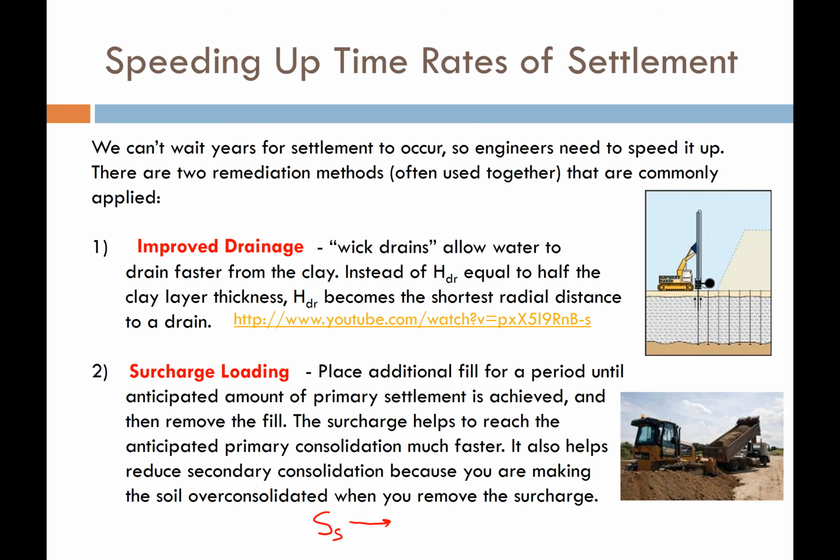So if I apply wick drains and I apply surcharge loading together, then we can really speed up the consolidation times, even for really thick, nasty clay layers that don't have very good drainage.